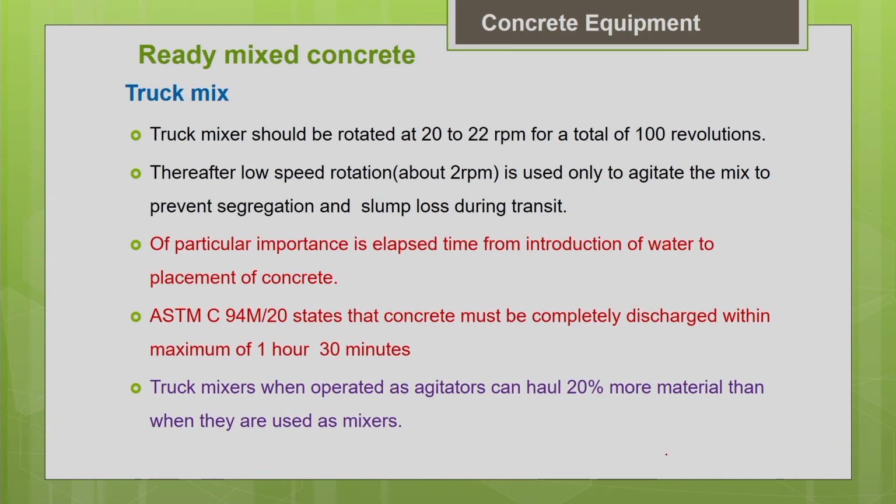So, if you are going for truck mix, in the sense that I am going to prepare the concrete inside the truck only, then there are some important guidelines to be noted. As you are going to prepare your concrete inside the truck only, you should rotate at the speed of 20 to 22 RPM.